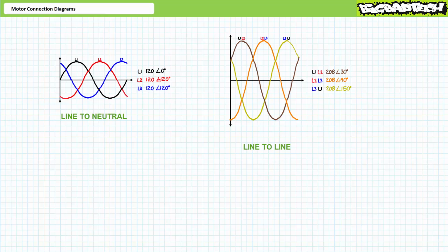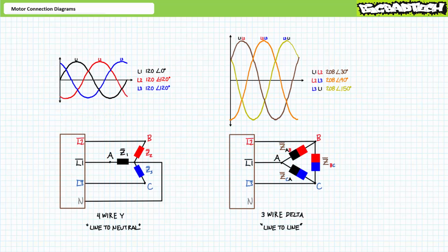Light industrial three-phase AC inside the United States is characterized by a 120-volt line-to-neutral and a 208-volt line-to-line value. Three-phase AC allows two basic options: Y-configured loads, which experience the lower line-to-neutral voltage, and delta-configured loads, which experience the higher line-to-line voltage. This is not what I mean by the term dual voltage. A single three-phase AC system with two available voltages, line-to-neutral and line-to-line, is still a single system. The term dual voltage more appropriately means two system voltages.